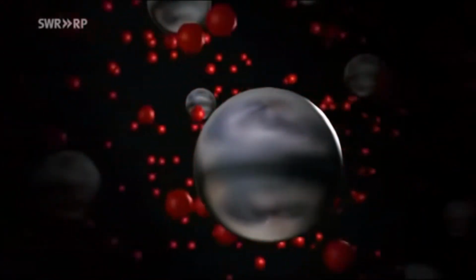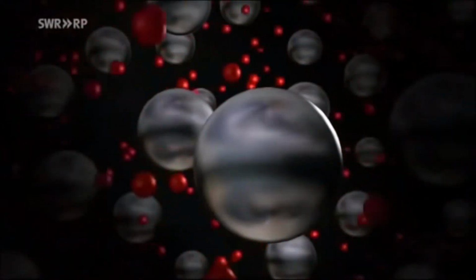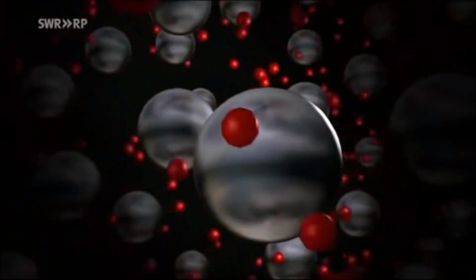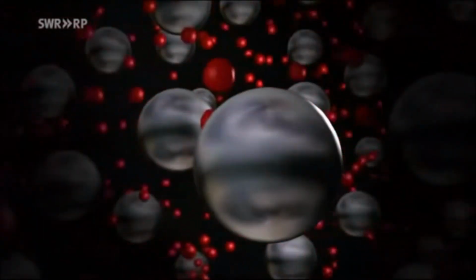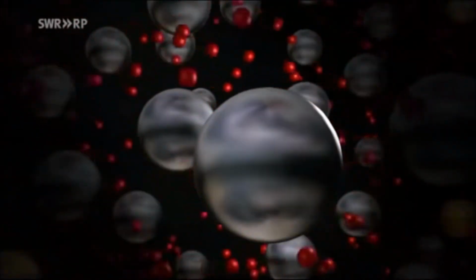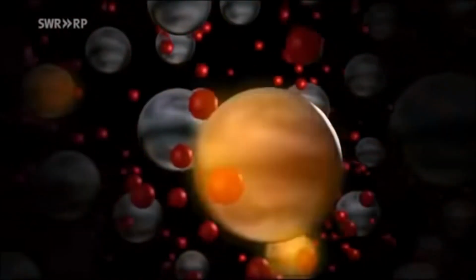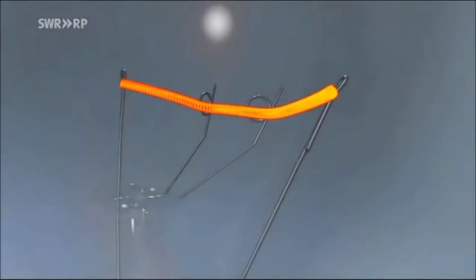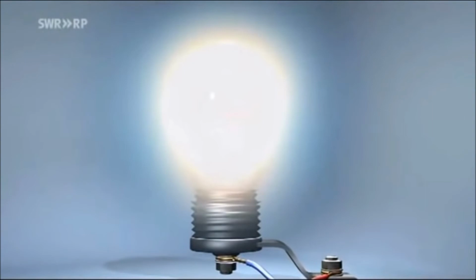The electrons flow along the wire. In the process, they bump into the particles that compose the conductor. The more of these particles that get in the way, the fewer electrons can get through, and the higher the resistance of that particular conductor. Every collision slows the electrons down. They lose energy, which is given off in the form of heat. Given the right material, a very thin wire can glow white hot in this way. In the incandescent lamp, this effect is exploited for lighting purposes.